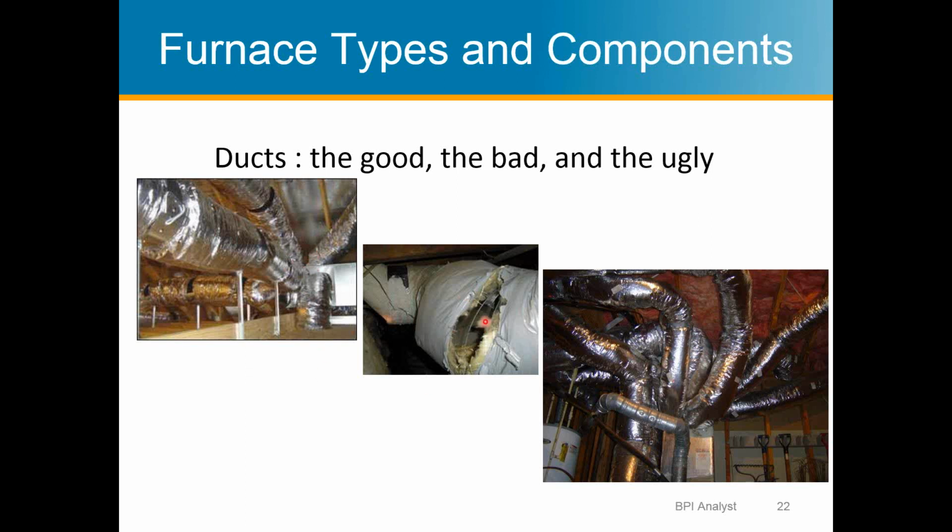So here's an example of a duct that's either disconnected or at least the insulation is torn. Ducts can also be metal ducts. These flexible ducts are cheaper, and that's why they're used, easier to install. The metal ductwork probably hasn't been really used for 20 years or so. There's nothing wrong with metal ductwork if it's already there and it's sized properly, and if you can insulate it, even better. So that's the ducts.